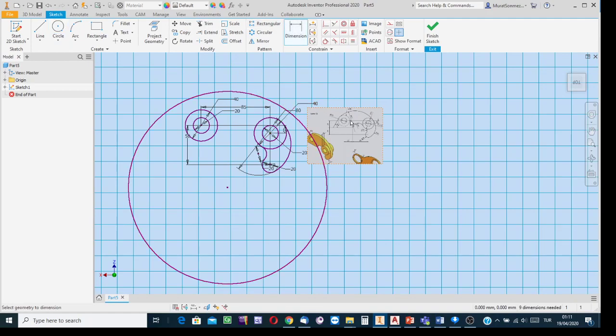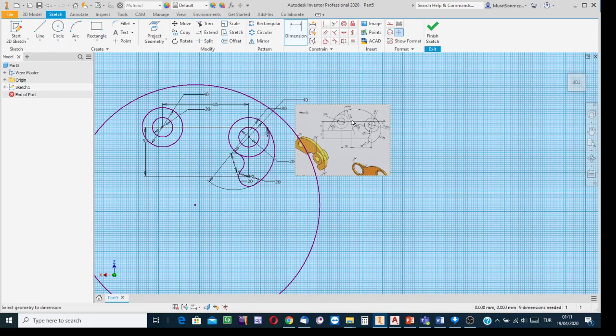Dimensional constraint. Well, 95 is the radius, so for the diameter, click into this box and test whether simple arithmetic is acceptable. 2 times 95. Instead of performing such a multiplication in your mind, just write the expression into this box. The asterisk in Inventor means the multiplication operator. And then say OK.